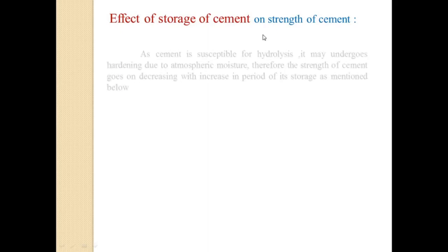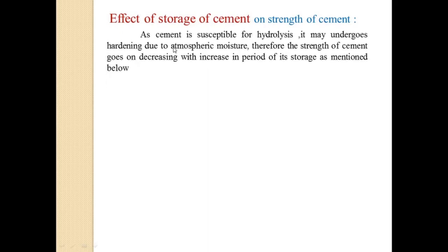Next is the effect of this storage on the strength of cement. As we know, cement is susceptible to hydrolysis. It may undergo hardening due to atmospheric moisture. Therefore, the strength of cement goes on decreasing with increase in the period of storage.